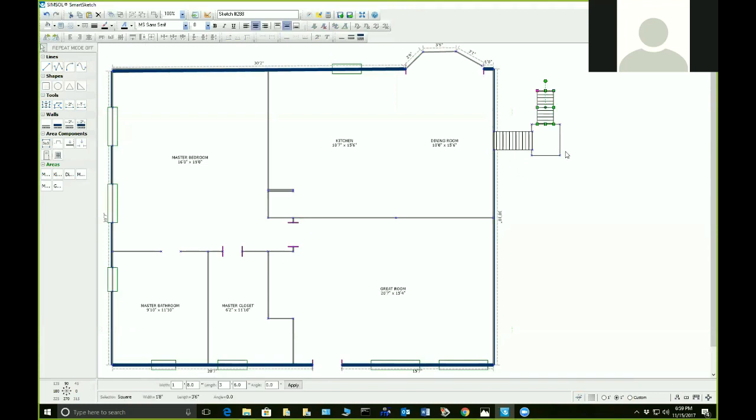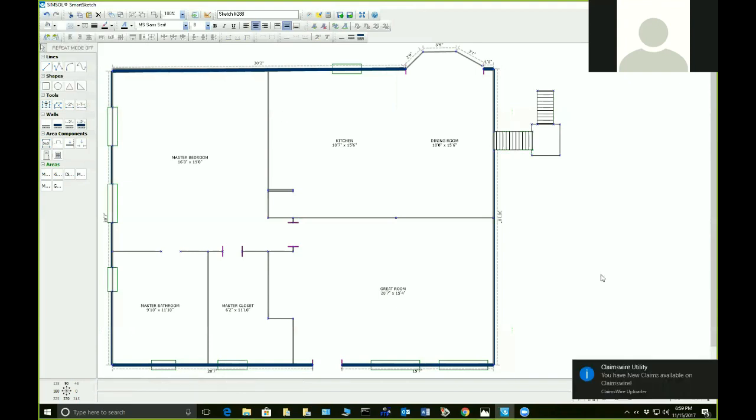When you first click on the pattern, it's going to be just the solid line. That's going to give you this, and it'll fill it in for you. On the horizontal type of stairs, select it, use your pattern, and then select the vertical lines, and that's what you're going to get. So that's how you can do stairways pretty easily. You just use a combination of the rectangle and the pattern. Okay, so that's how you could do that one.